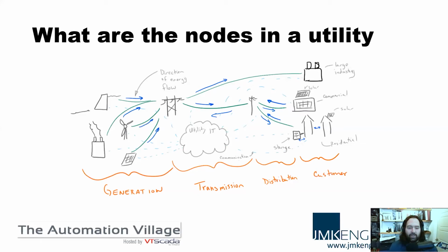Generating stations typically interface with the transmission system, and then you have a step-up transformer. Now, that's the demarcation point, right? But for a utility, it could be on either side of that transformer, not important. Transmission substations, that's where all the bulk power is switched, stepped up, moved around, and then down to the distribution substations that take it to the last mile.